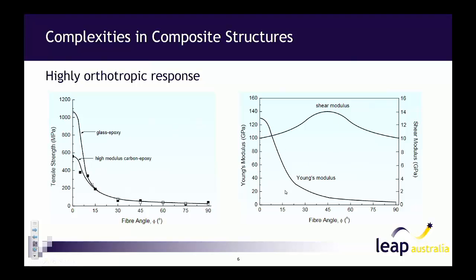And when we're loading across the fibres, we lose a lot of that elastic modulus. That's because when we're pulling down the fibres, they're very stiff and strong. When we're pulling across the fibres, we're actually loading the resin in between the fibres. So it's really important that you either have all your load paths nicely down your fibre direction, or you account for the loss of strength and the loss of rigidity when it's loaded across it, and that's where this finite element simulation comes in.